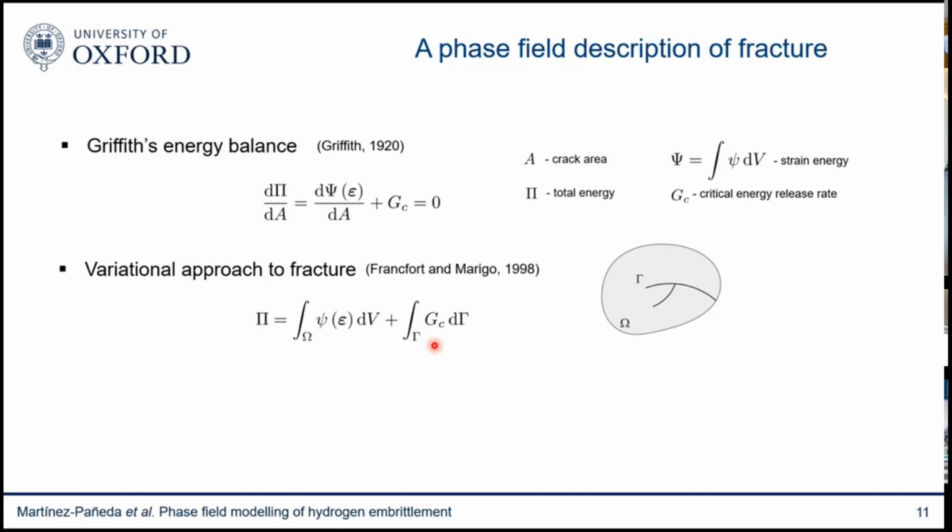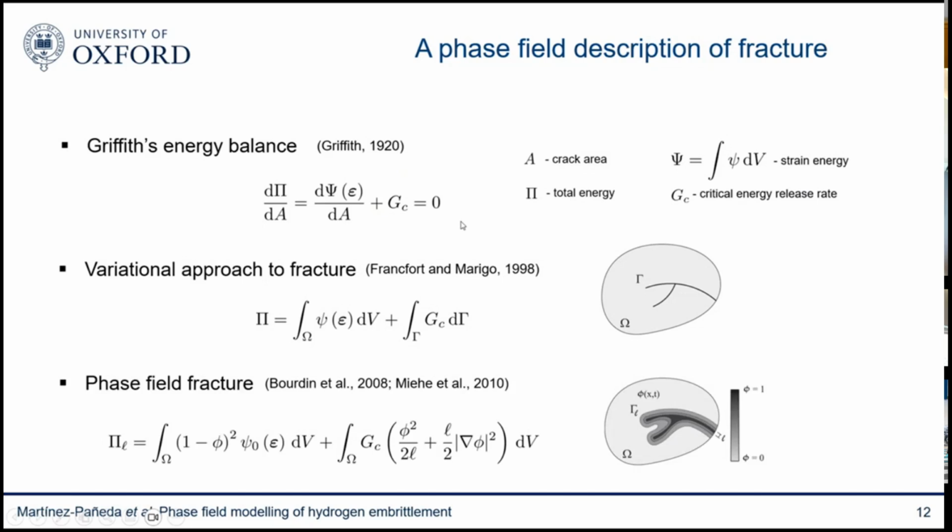And this is the reason why we decided to convert J, energy release rate, to stress intensity factor and move ahead with the stress intensity factor approaches, even though they are equivalent, because it's very difficult to solve a system like this. But phase field gives you an opportunity to do so, because phase field is a little bit like a marker. So it tells you where the crack is.